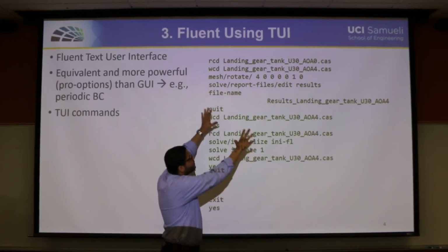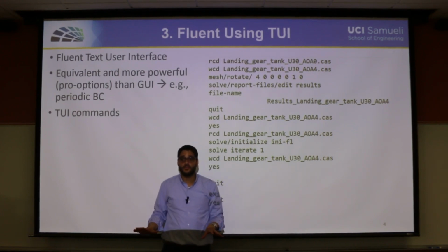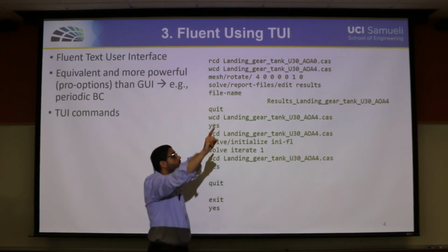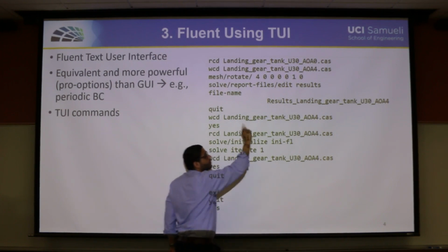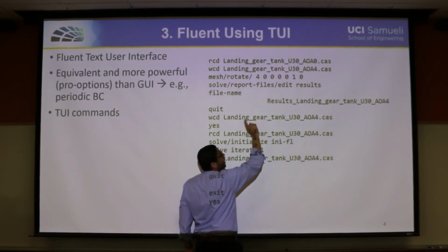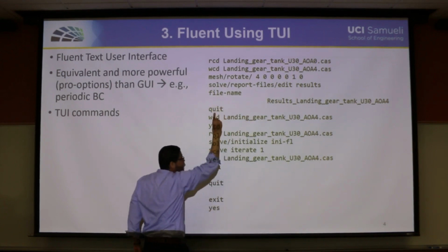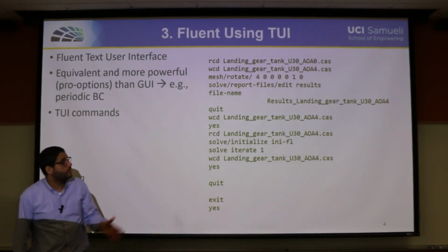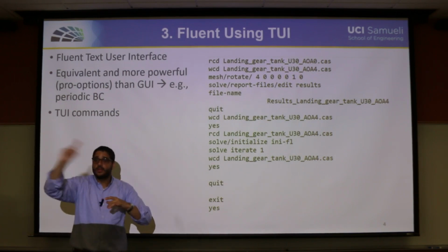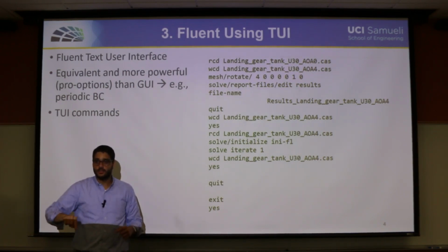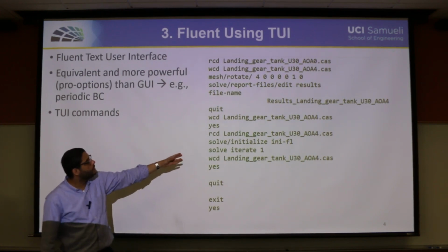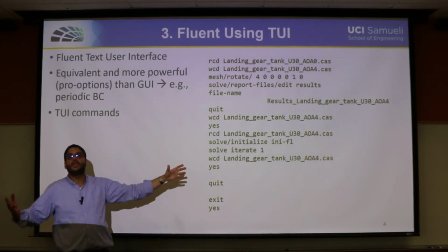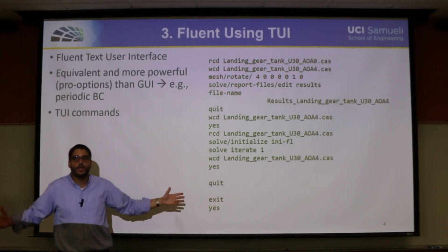So if someone's trying to do this through the graphical user interface, you have to be very sharp, very focused, to be honest, to go through all of these nodes, all of these menus. And do not forget to change the value for the results, for the output value, the name of the file, the angle of attack, etc. So it takes a huge time and focus to do it. And the bad thing is that you have to open Fluent and click those clicks at each case. Just count the number of clicks and the number of cases that I have. I did it once, it took me around a complete day. And I was sure that a couple of cases were wrong and I missed something.